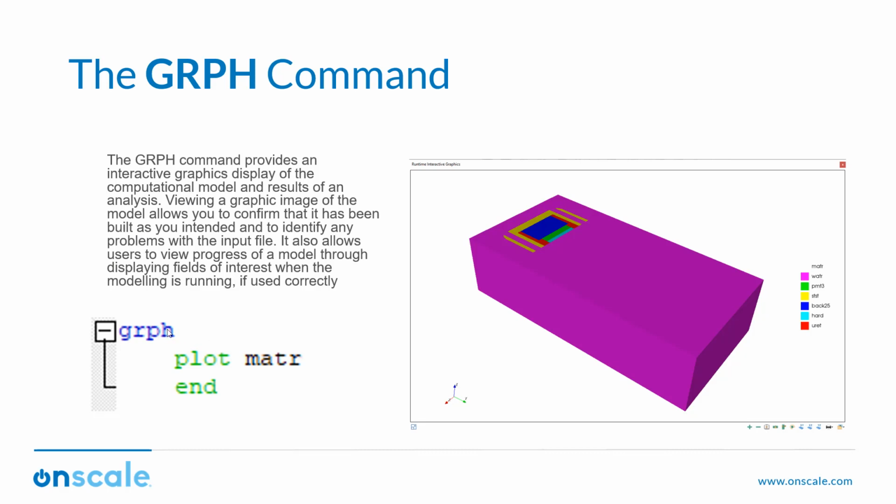I call it graph, but if you look at it very well, it's grph, because the number of characters is limited to 4. So sometimes you just write the script, forget about that, and write graph with an A in between, and it doesn't work. So the first thing to be careful about is do not put the A, it's grph.